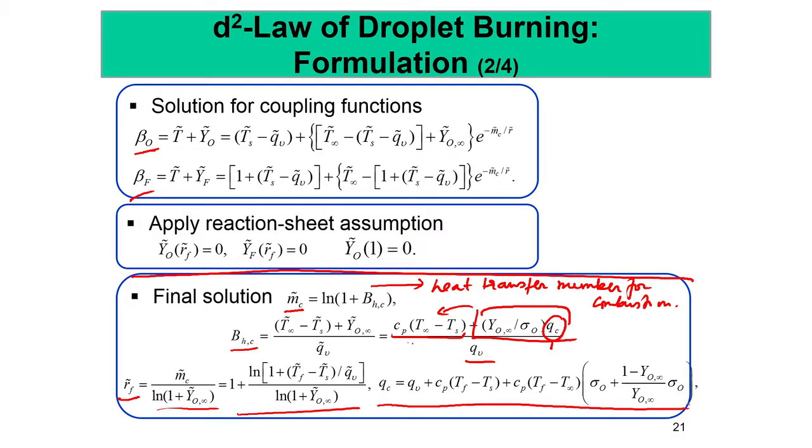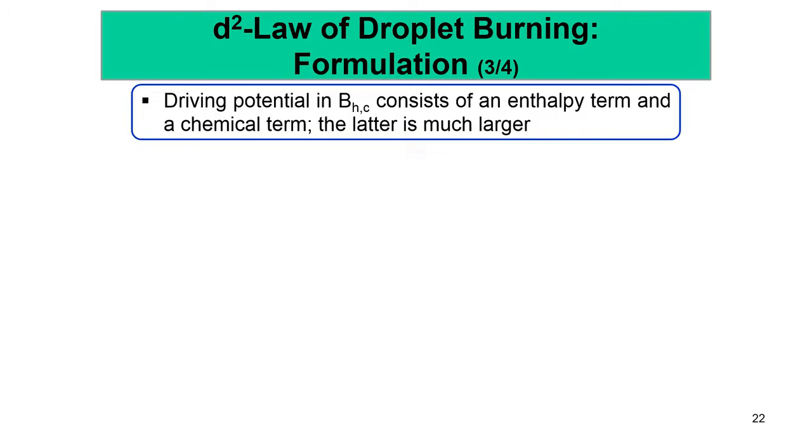Once again we can get this temperature in an implicit form, where we show that this QC, the heat of combustion, is essentially the same thing. There is no fuel mixture now because it is purely droplet. So 1 kg of fuel, when you burn it, raises the temperature from Ts to Tf, and raises the temperature from T infinity to Tf. Of course, these are stoichiometric balances which show that the burning is stoichiometric, but it is also used for the latent heat of evaporation. So by the same argument, it is essentially the adiabatic flame temperature, but with consideration for the latent heat of evaporation.